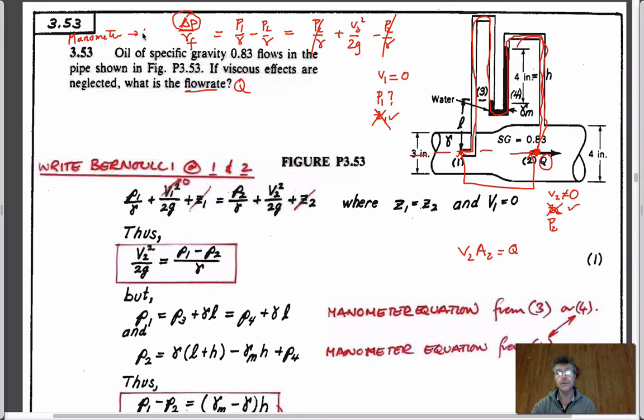to get delta P. It will be a function of the gauge fluid. Actually, delta P is just going to be equal to this height minus the, is what it will turn out to be. So delta P is equal to the height differential multiplied by the unit weight of the gauge fluid, not the fluid in the pipe. This is the pipe fluid. And so be aware of that.